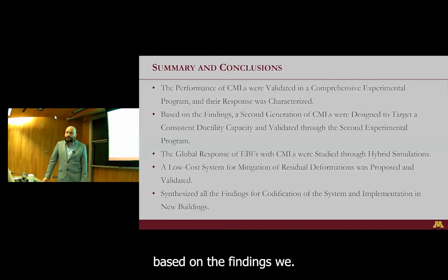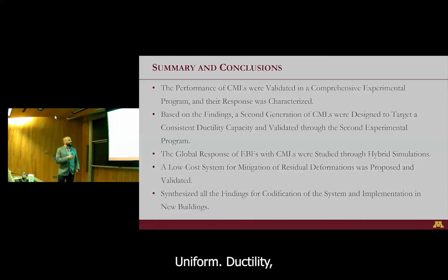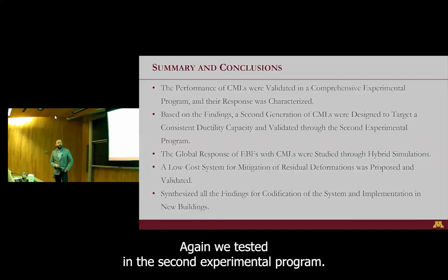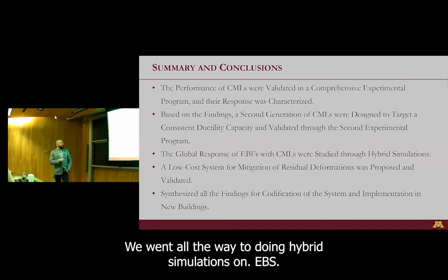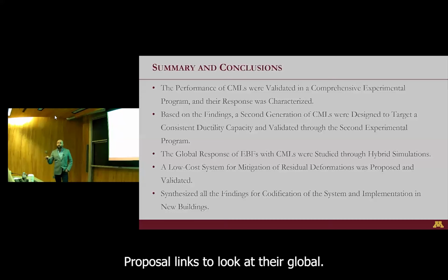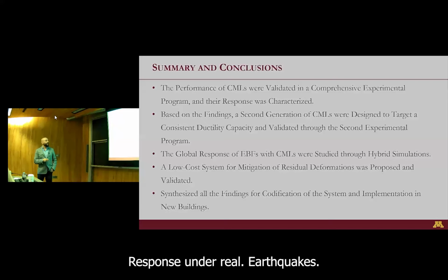Based on the findings, we looked at a second generation of cast modular yielding links, and they were designed to target a more uniform ductility, which again, we tested in the second experimental program. We went all the way to doing hybrid simulations on EBFs designed with the proposed links to look at their global response under real earthquakes.